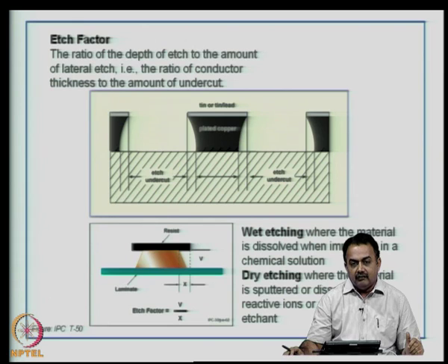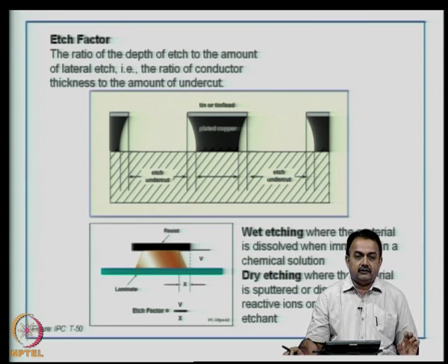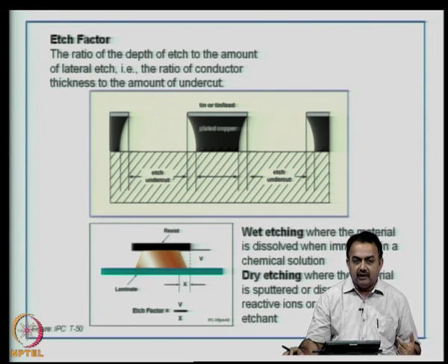There is going to be a lot of difference between dry etching and wet etching. Wet etching is typically very useful, advantageous for large area removal of copper, whereas dry etching typically does not work well for large volume manufacturing and you can use dry etching for prototyping.